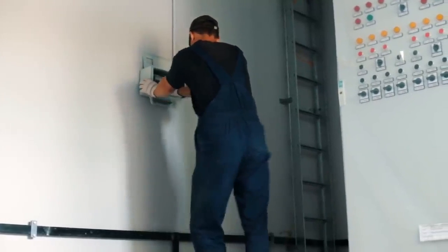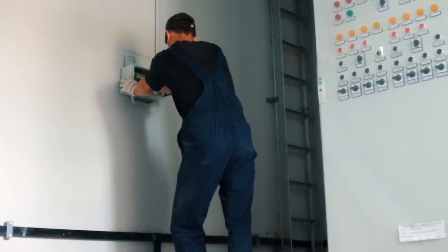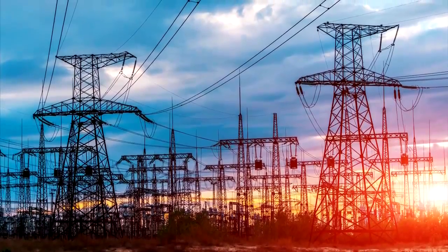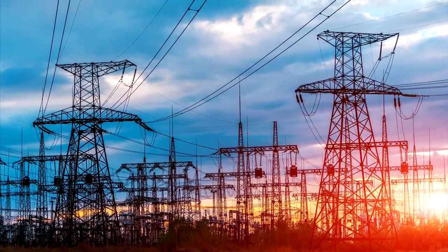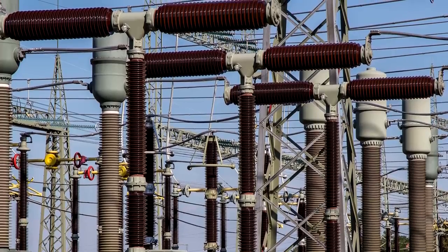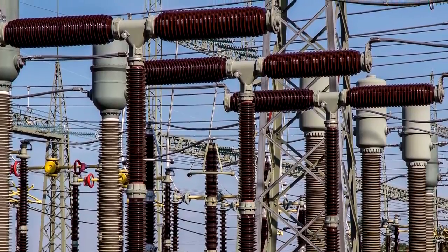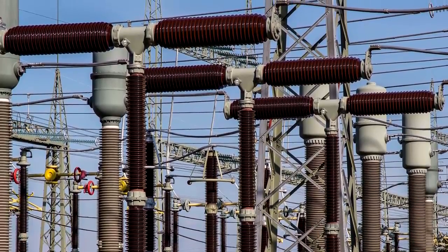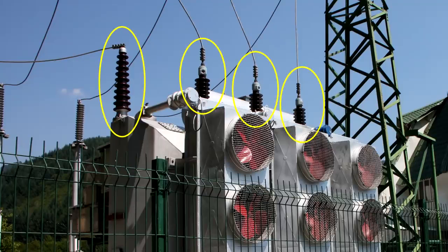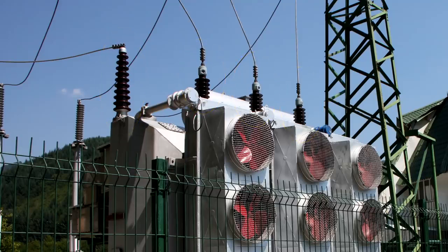The final and most important role of a substation is that it be safe for electricians and linemen to inspect, repair, and replace equipment. Substations are usually the only locations where extra high voltage power lines get close to the ground, so safety is absolutely critical. The buswork running along the substation is protected from short circuit by large insulators to avoid arcs to ground. Even the connections into each piece of equipment are done through a device called a bushing, which maintains a safe distance between energized lines and the grounded metal housings.